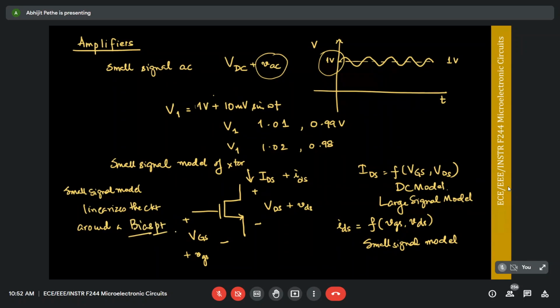So we'd be interested in two things, therefore. The model becomes a function of the bias point. And this is basically the crux of design, in trying to understand how you're going to bias the circuit, and then based on where you bias, the circuit properties are going to change. So not only do you worry about the transistor sizes and the voltage sources you're applying, you also have to worry about how you are biasing the circuit. We'll spend a lot of time in this class talking about biasing circuits. How do we bias these amplifiers so as to get the required gain or the required properties of the amplifier?